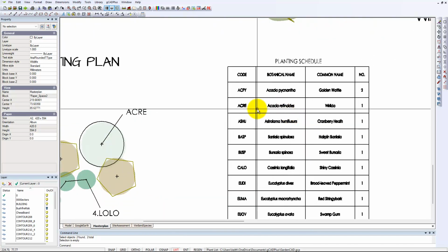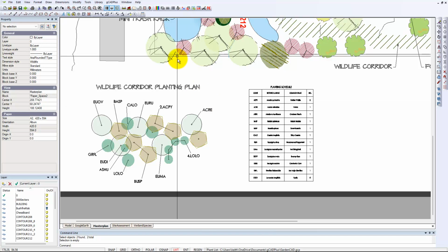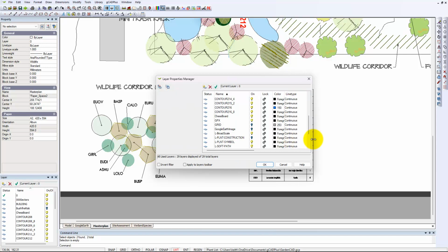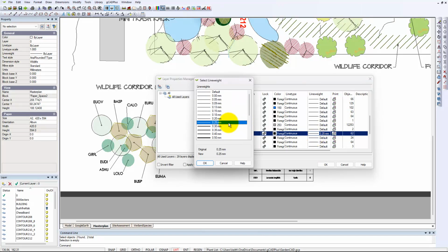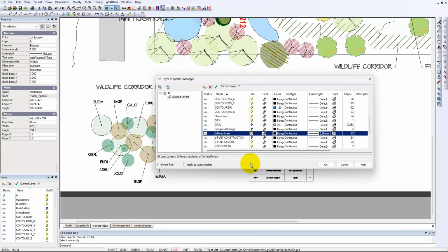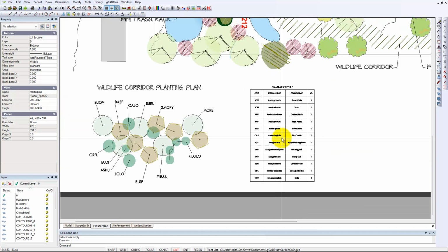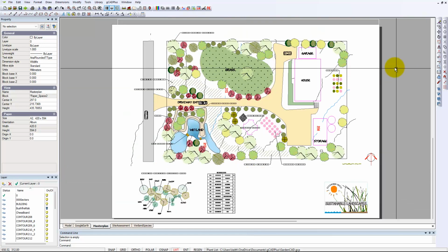You may notice that the thickness of the text looks a little thick there to me, but you are able to go into broadscale, L broadscale, and let's widen that. Notice that 0.25 is line weight set by layer, so we can bring that back to 0.15. OK that, and we get a finer text that will print fine, particularly as this is quite a large sheet.